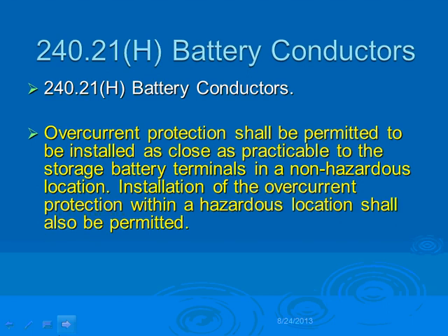But if you don't know, and a lot of people don't know and don't want to take these Fs, they go with the largest overcurrent protection device, a cover-your-butt type design. So with a 100 amp circuit and a 100 amp transformer, you can put either a 125 amp fuse on the primary side or a 250 amp fuse. Look at that range between them. So I tend to go lower than 250 just for protection, but then I run the analysis on it.